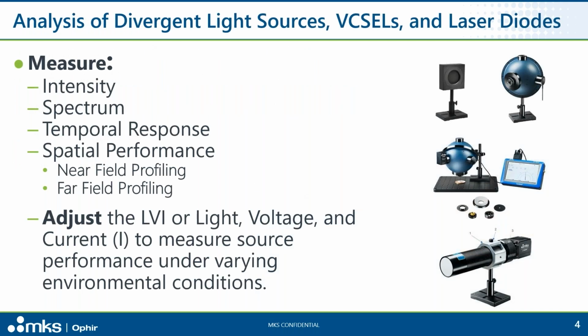What do we measure? Intensity. Power, or energy for a pulsed source, or a source that may be pulsed in whatever the application or device is used. Pulsing can save battery life if that is a concern for the application. We also want to measure spectrum, the center wavelength, and spectral bandwidth, or color where the device is used. Center wavelength, bandwidth, and optical noise change with temperature.